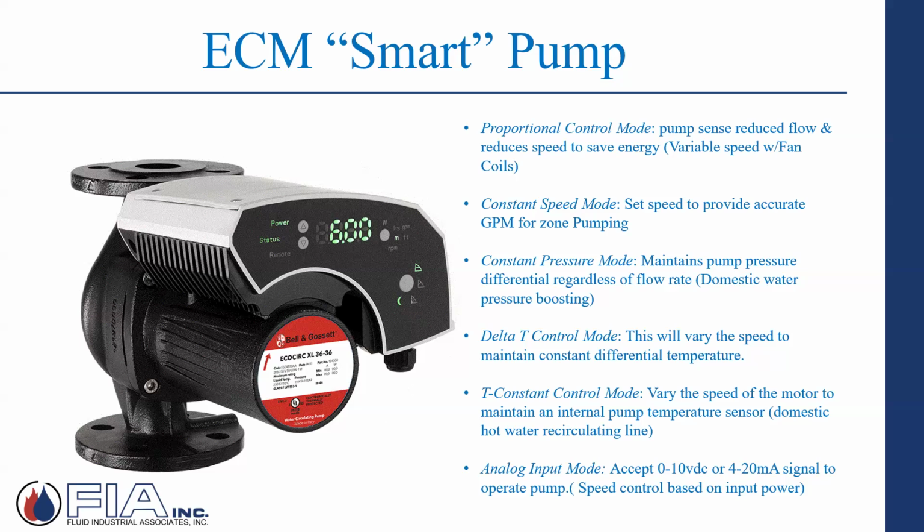And if that 20 gets tighter, because the firing rate's starting to reduce the BTU output and the flow's too high, I'll reduce the power signal to the pump, which controls the speed, the RPMs. Like we just talked about, RPMs affect GPMs, and I'll reopen that delta T back to the desired, say, 20 degrees across the heat exchanger. So that's how it's happening on the boilers.